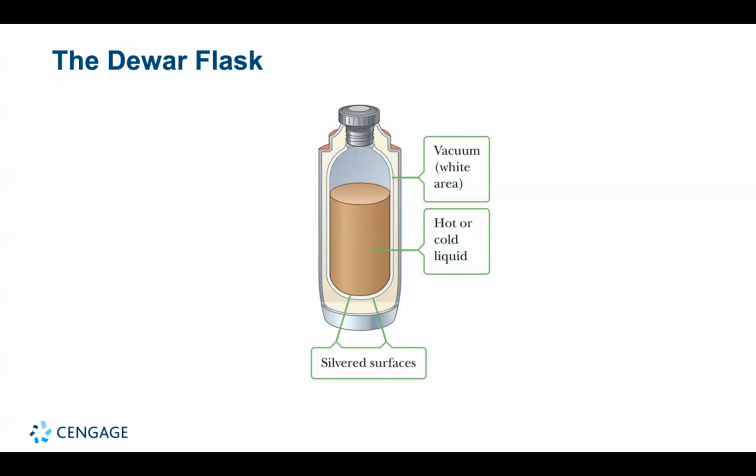Some of the principles of the thermal bottle are used in the protection of sensitive electronic instruments in orbiting space stations. For half of its orbit around the Earth, the satellite is exposed to intense radiation from the sun, and the other half, it lies in the Earth's cool shadow. Without protection, the interior would be subjected to tremendous extremes of temperature. The interior of the satellite is wrapped with blankets of highly reflective aluminum foil. The foil's shiny surface reflects away much of the sun's radiation while the satellite is in the unshaded part of the orbit and helps retain interior energy while the satellite is in the Earth's shadow.